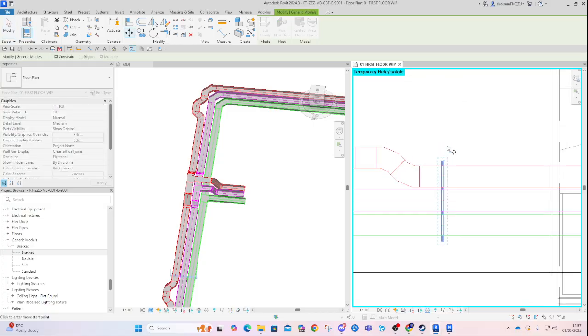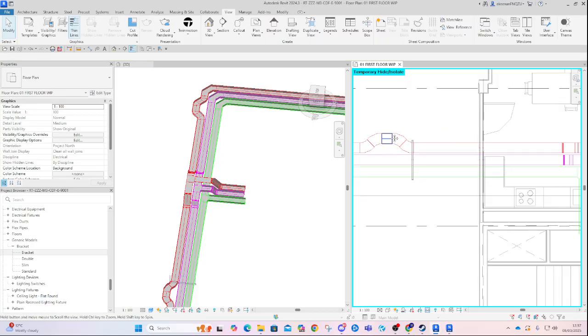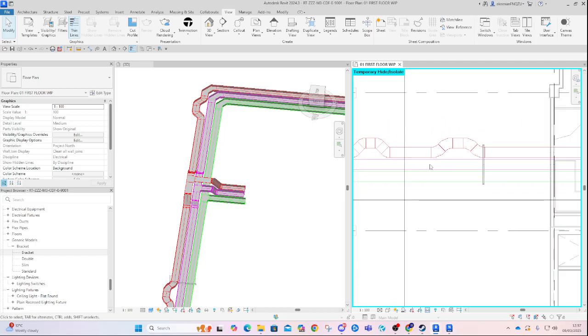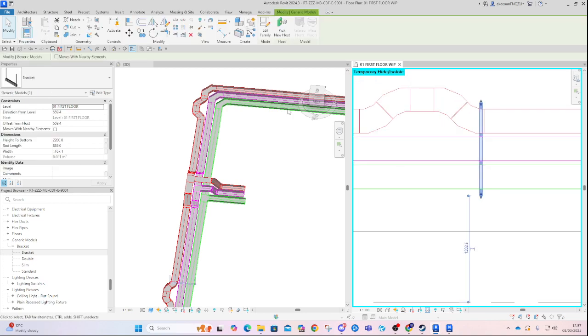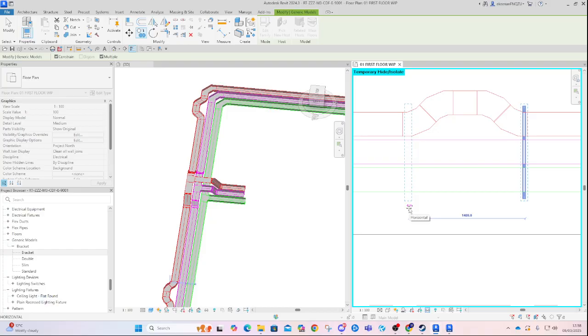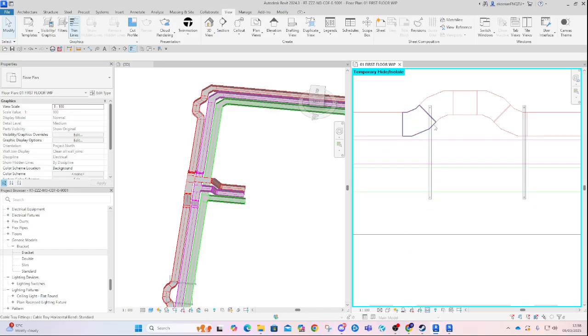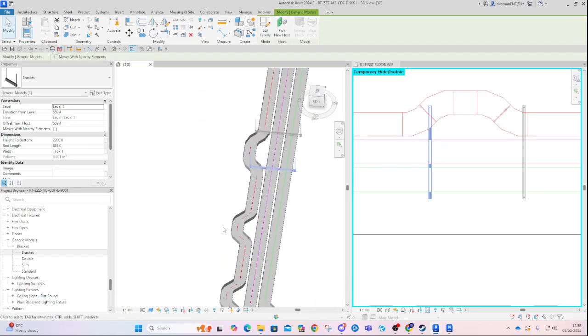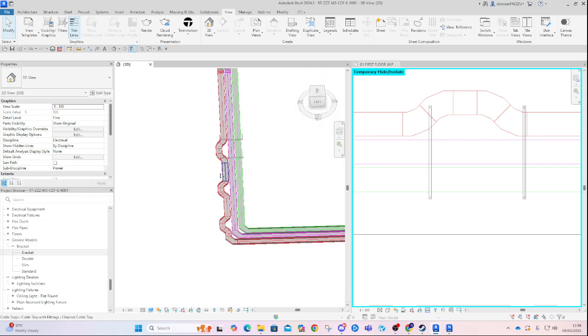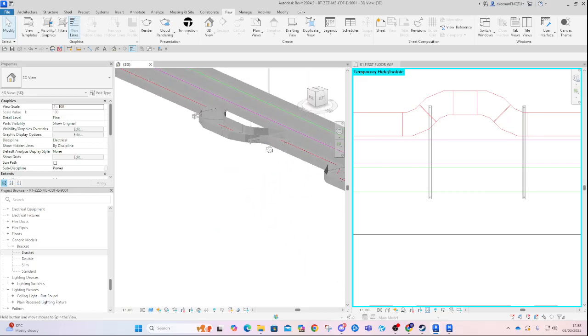Now I am going to move it, because this is a bend piece. I'm just going to sort the hard parts out. The straight pieces aren't a problem, but getting as tight to 1200 as I can at a funny bend is. For example, here you can see the threaded rod will protrude through the cable tray above, which would be a clash in Navisworks, which means it wouldn't be possible to install it like that on site.